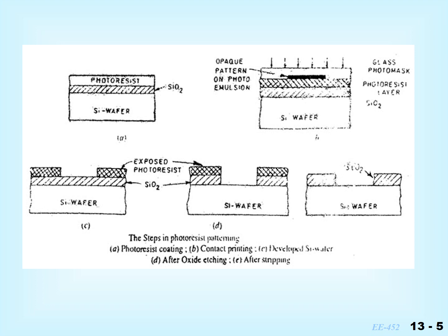So here you can see the step-by-step process. Before photolithography, oxidation has taken place. So you can see in figure A, there is an entire silicon dioxide layer over which the photoresist has been applied. Now, using a certain photomask, this photoresist is exposed to certain radiations.